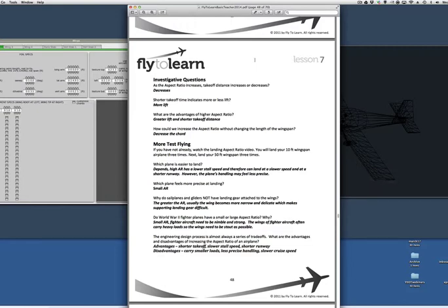And the more aspect ratio you have, again, you have less takeoff distance, which is great to fly. But what happens is, along with the advantages, you find out there's disadvantages. First of all, you can usually carry smaller loads, and your handling isn't quite as precise, and you've got a slower cruise speed.